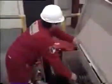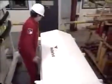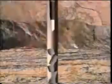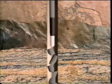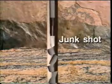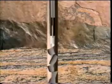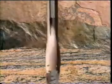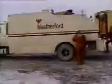Occasionally, in open-hole fishing, junk may be too large and must be broken up into small pieces to be more easily retrieved. In these instances, a powerful explosive charge run on drill pipe is placed directly on top of the junk downhole. With the shot in position, a Go Devil electronic charge carrier is dropped inside the drill pipe. When it strikes the charge, it safely fires downhole. The smaller debris is then recovered.